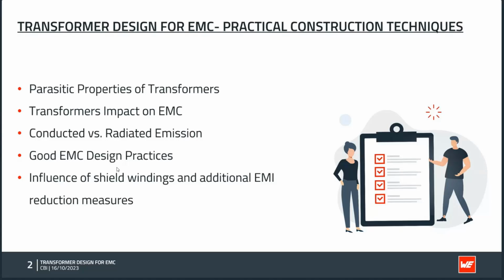So I will really focus on the internal construction, how the windings are positioned inside the winding window, and so on. I will show a few good EMC design practices that we always try to follow. In the end, I will also show the influence of shield windings on the EMI behavior and additional measures we can take.